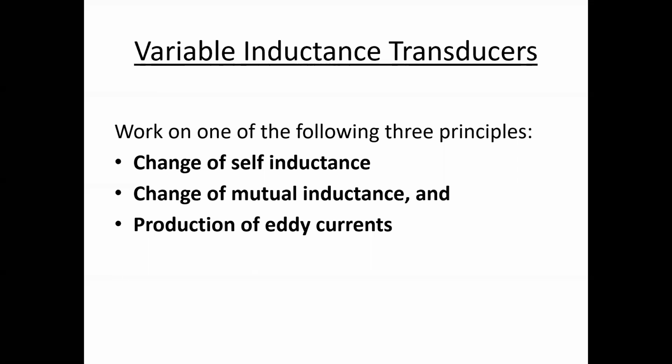And in today's class, mostly I am going to discuss some basics of inductive and capacitive transducers, or their working principle. So if I start with the inductive transducers, they basically work following the principles of change in self-inductance, or change in mutual inductance, or by the production of eddy currents.